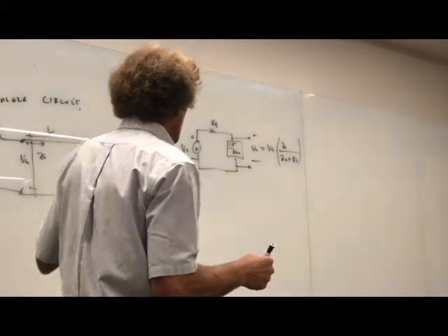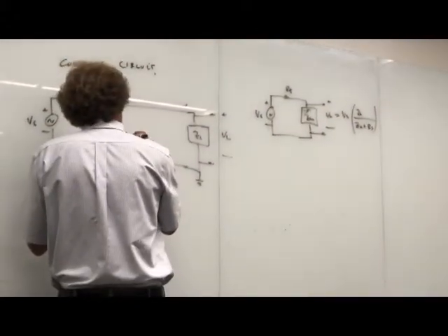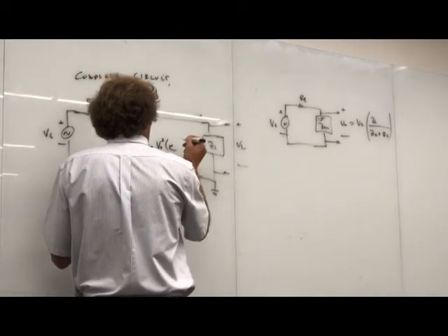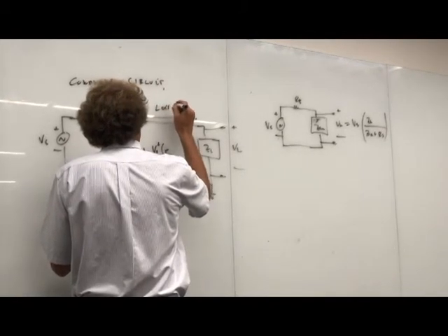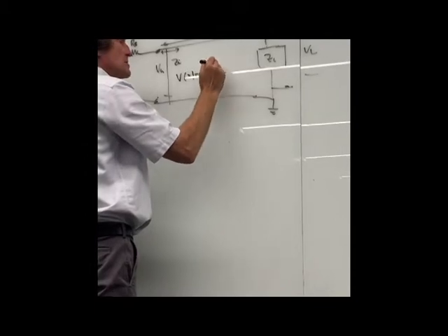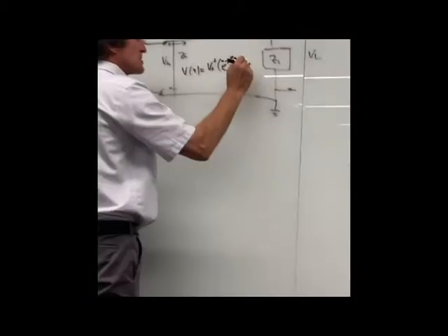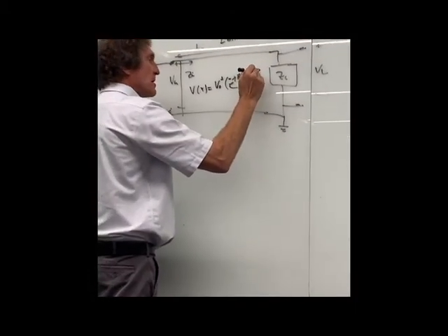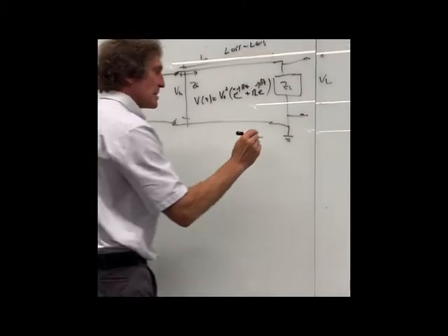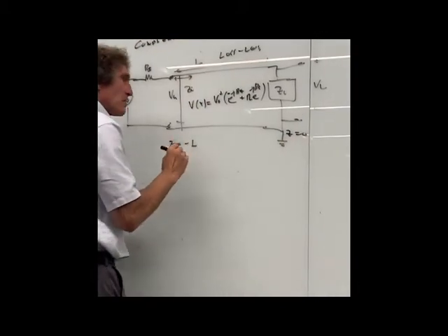That's as easy, and for a circuits problem, that's one of the most basic. Now, if we have that, what is Vn? Isn't Vn really the voltage V of Z equal to V0 plus times e to the minus j beta z plus reflection coefficient times e to the plus j beta z? Let's do this as lossless, by the way, so we don't have a gamma here. But remember the distance L, this is at Z equals 0 here, and this would be at Z equals minus L.